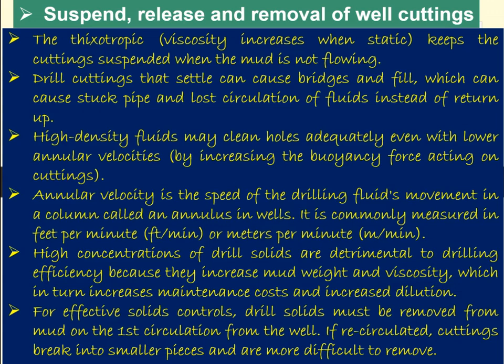The next property is that drill cuttings that settle can cause problems, as I have discussed. If by chance all the drill cutting materials get settled down, what will happen? It will cause bridging and fill, which can even cause the pipe to get stuck and lost circulation of fluid, instead of returning up. The fluid will not come back, and the borehole drill pipe, or drill rod, can be stuck because these drill cuttings get settled. So if we do not properly utilize the drilling fluid, it can get stuck.